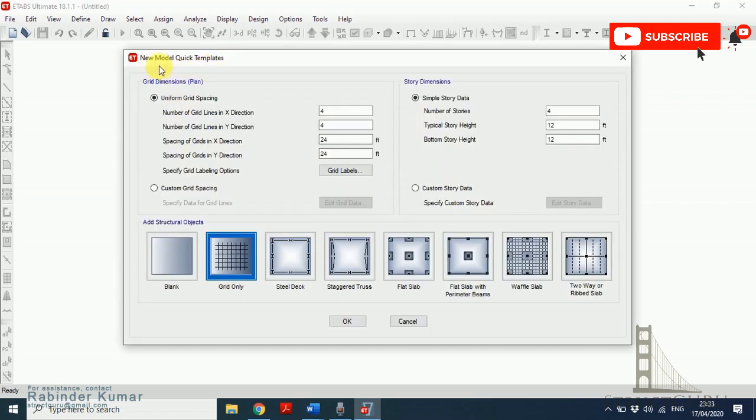This brings you to the New Model Quick Templates. I will discuss this panel in detail as it is very important to model a structure. So first understand why we have to define the grids and story data at the start. Grid lines are reference center lines of your structure.